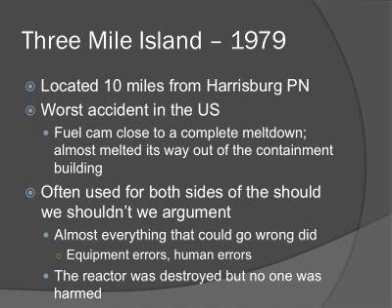So a pressure valve was then opened because this is pressurized water, right? They opened the pressure valve to try to release some of the pressure to keep it from overheating. Well, when they opened the pressure valve, they had another equipment failure, and they tried to close it, and the computer said, yes, the valve is closed, but the valve was not closed. And so they thought they had fixed the problem. The pressure started going down, so all the readings were saying, okay, we've got this under control.